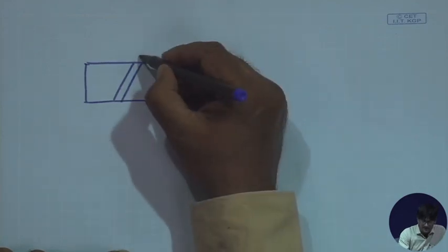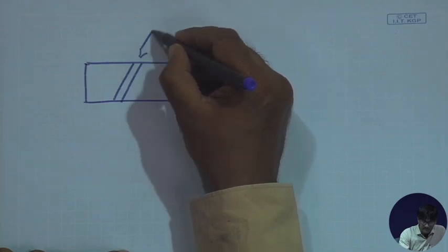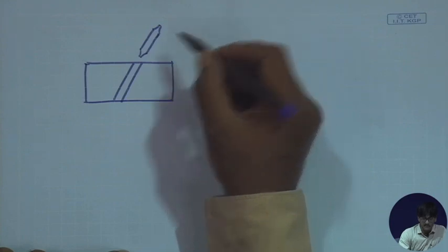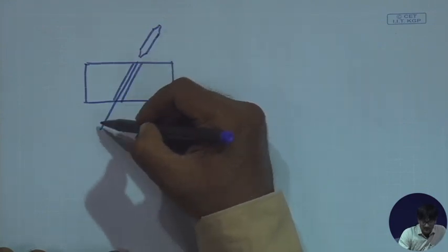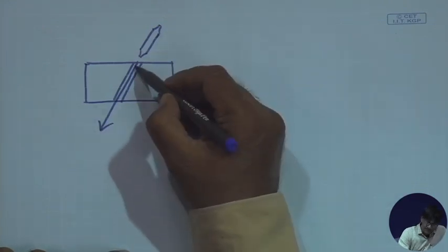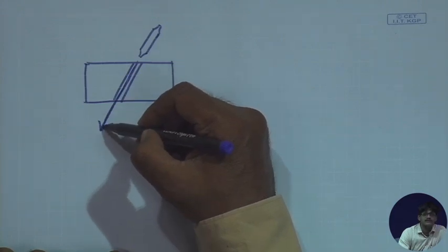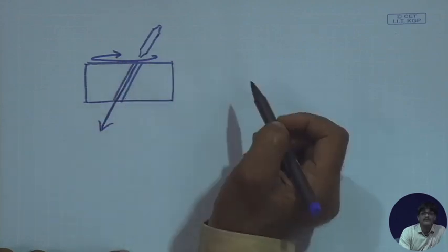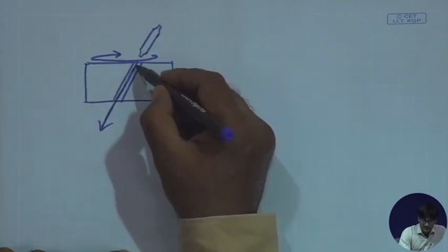So, the cutter, which is once again that same cutter that we have used for spur gear milling, has to pass this way now. We have ensured the motion to be in this direction by the combination of rotational motion and straight line motion.